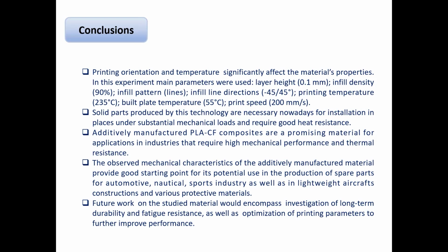The printing temperature, as specified for the material, was 255 degrees, and the build plate temperature about 55 degrees. But the first time we printed with some kind of extreme speed, about 200 millimeters per second, because early generations printed at 50, 60, and 80 millimeters per second.